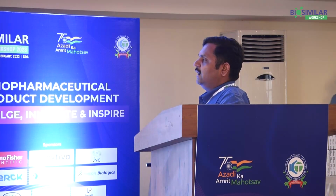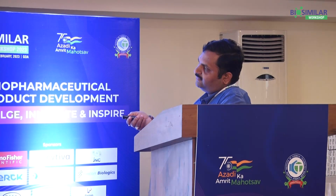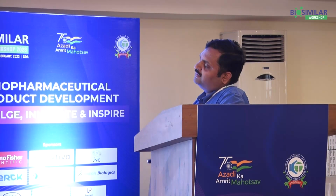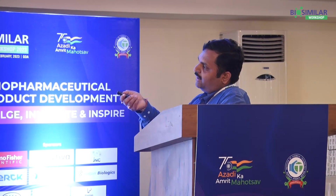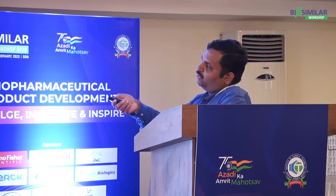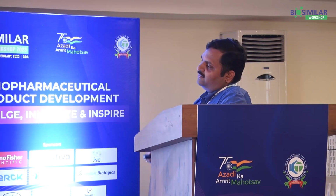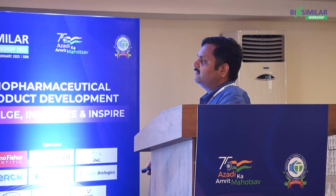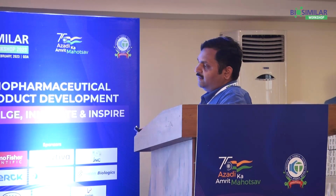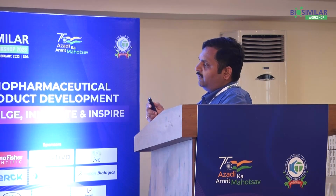In the upcoming slide, we compared different breakthrough target percentages, like 60 and 80, and we can see the highest productivity is seen with the highest target breakthrough at lower residence time. But at the higher residence time, there is no impact. So there is an interaction between the target loading capacity and productivity.